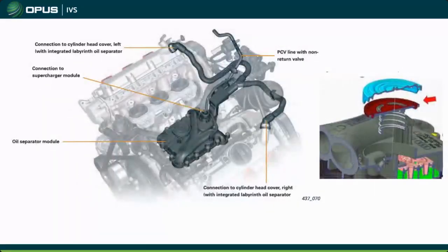So let's talk about the 3 liters, because these had a lot of issues also, and they had the same kind of issues that the 2 liters had, which was that they pulled too much vacuum, and their solution was to lower the amount of vacuum, right? Lower your crankcase pressure. So here we have another system where they've smushed a bunch of things together.